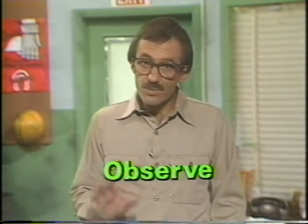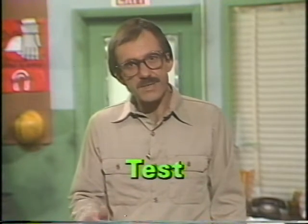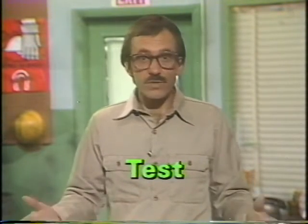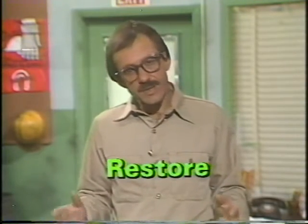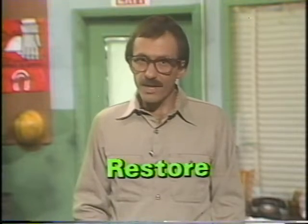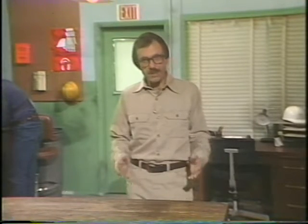Now, this means you need to prepare, to observe, diagnose the problem, and then test the system. Then once you've located the problem, you need to repair it, restore the instrument and the system to service, and finally, document the problem. The amount of time you spend on the different parts of the procedure will depend on the amount of experience you have. The more experienced you are, the more likely you'll be to troubleshoot the problem more quickly.